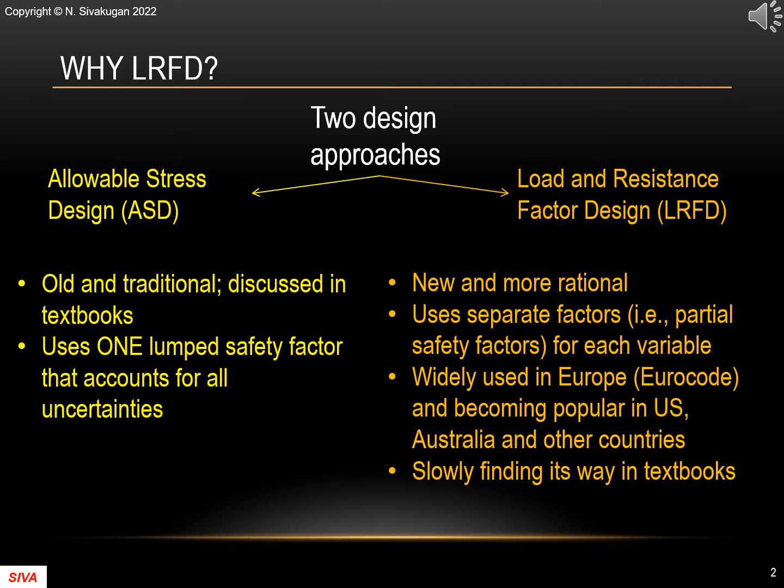There are two different ways of looking at a geotechnical design. The first one is the allowable stress design, ASD, also known as working stress design, WSD. This is what we have been doing for decades and is still being used and discussed in textbooks. The load and resistance factor design, LRFD, is relatively new and is increasingly becoming popular worldwide and is slowly finding its way into the textbooks.